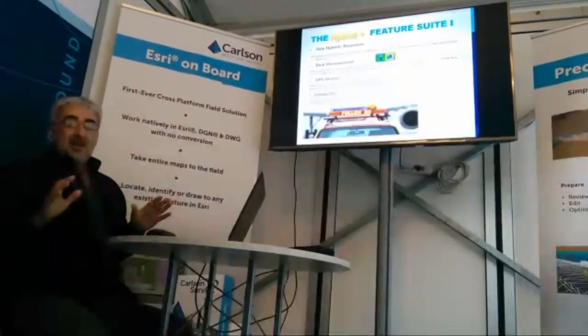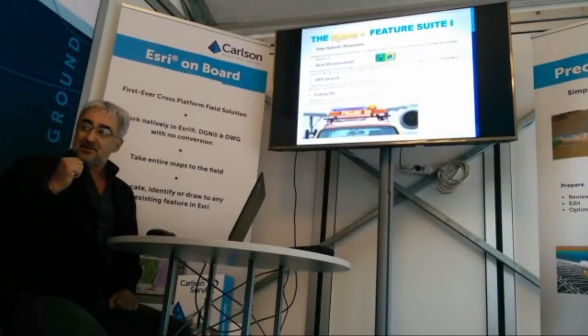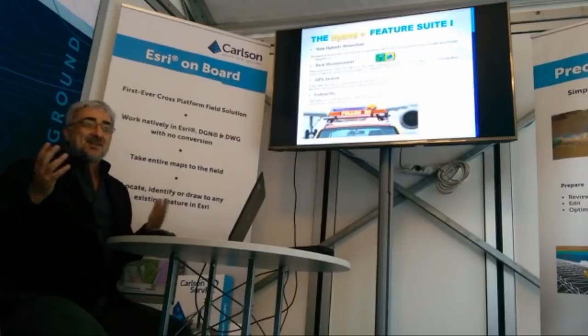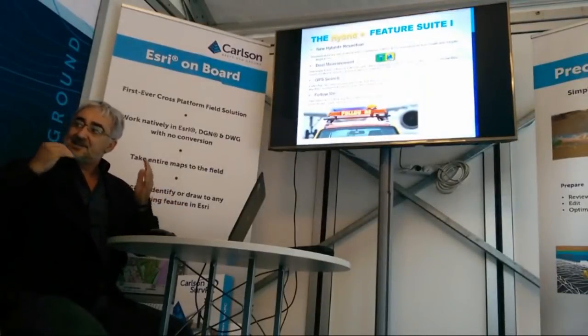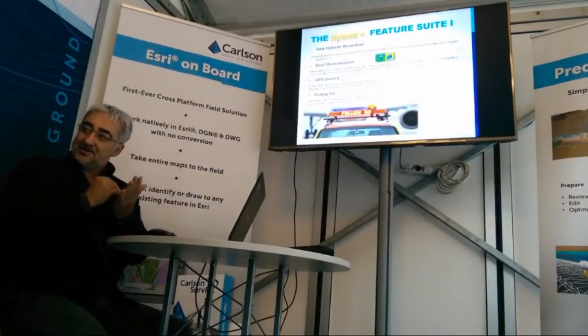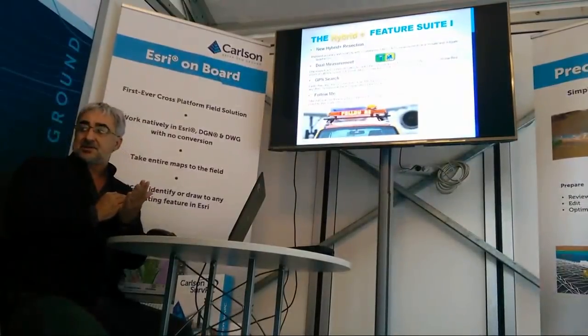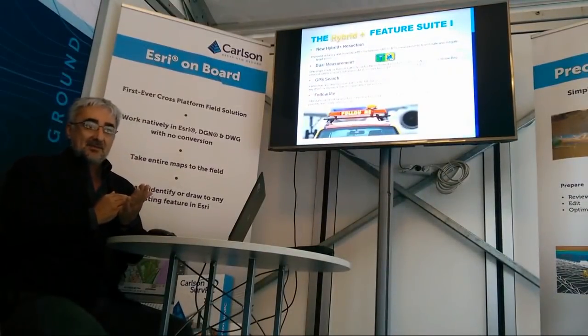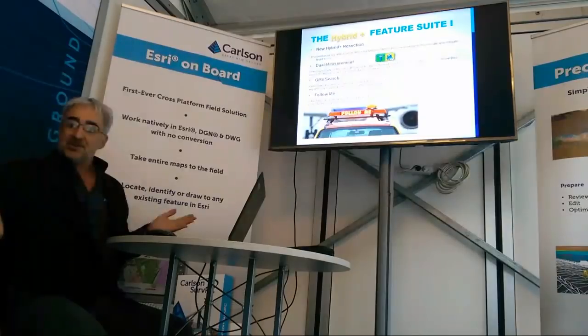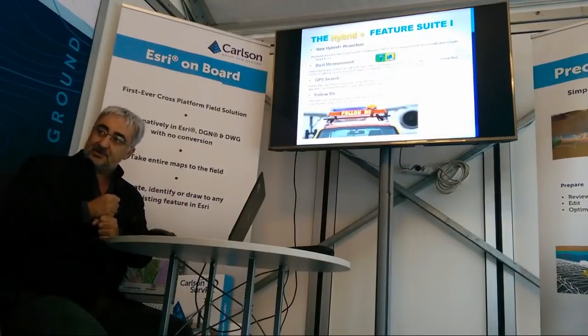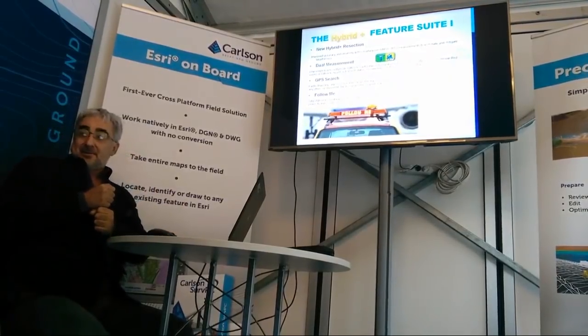You will see we have hybrid measurement. Hybrid measurement is simple, but it's nice. It's simultaneous reading of GPS and total station. What that means is we are reducing to only one occupation first, so only one-time errors, right?